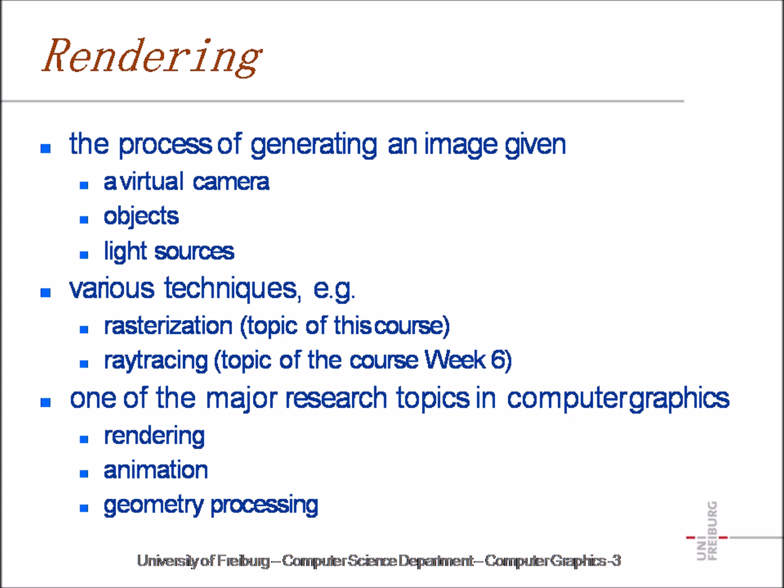The software like Maya or 3D Studio Max containing a virtual camera is made up of mathematical calculations that determine how the object will be rendered based on the location and angle of the virtual camera in the software program. It means, as with a real camera, when working with a virtual camera in 3D animation software programs, you can also use functions like pan, zoom, or change focus and focal points, etc.